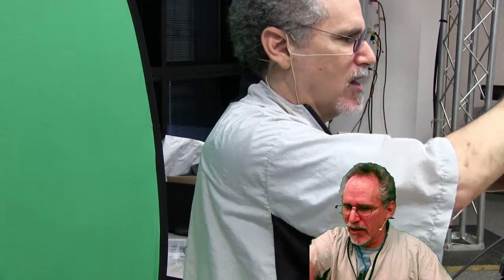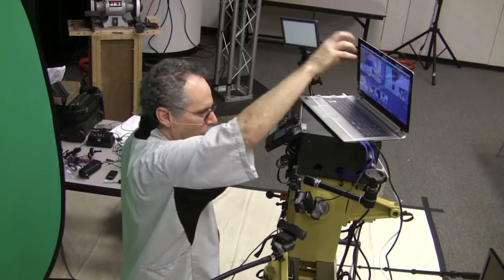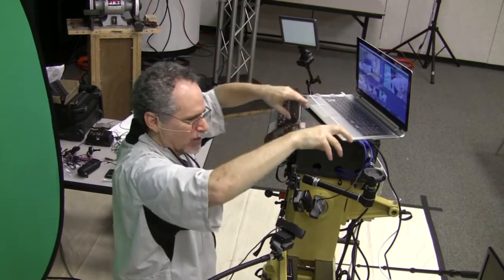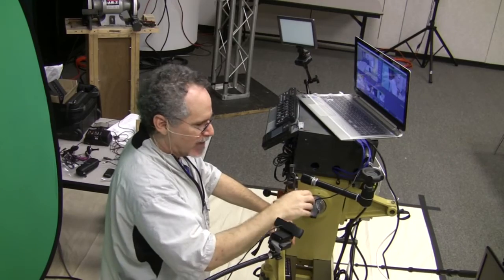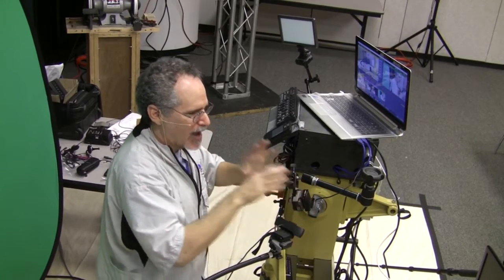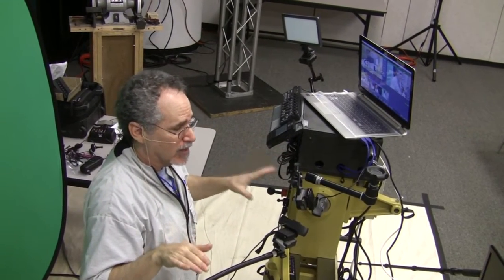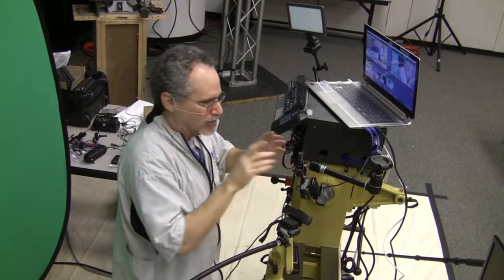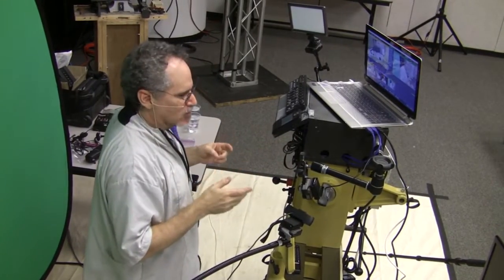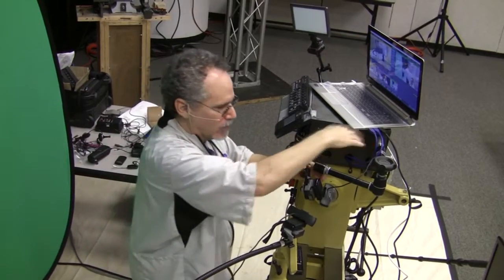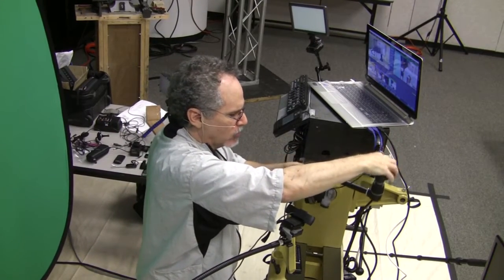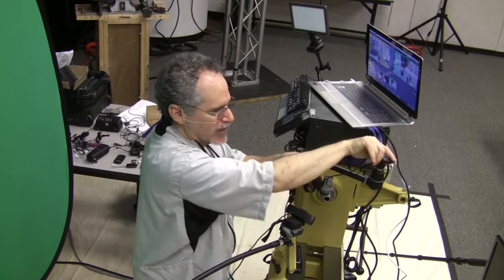What Lauren said is that when possible, don't do what I'm doing here, because I'm attaching this to something that's sitting on the headstock. Put it on a separate stand, or have it come down from your ceiling or whatever, so that if your lathe is vibrating, your camera isn't jerking all over the place. Try to isolate the camera from the lathe wherever possible. But in this case, I wanted to demonstrate a couple of things. One is that however you do it, you want to make it easy for you to maneuver the camera.